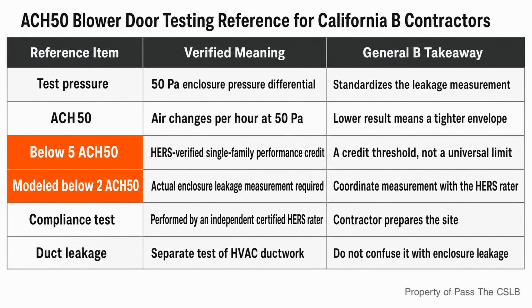Documentation also helps. Air sealing details can disappear behind insulation, wallboard, cabinets, and finishes. Inspection records, photographs, trade sign-offs, product information, and a documented pre-close walkthrough can make corrective work easier and clarify what was verified before concealment. The required project process controls which records must be retained, but casual memory is a poor substitute for an organized close-in inspection.